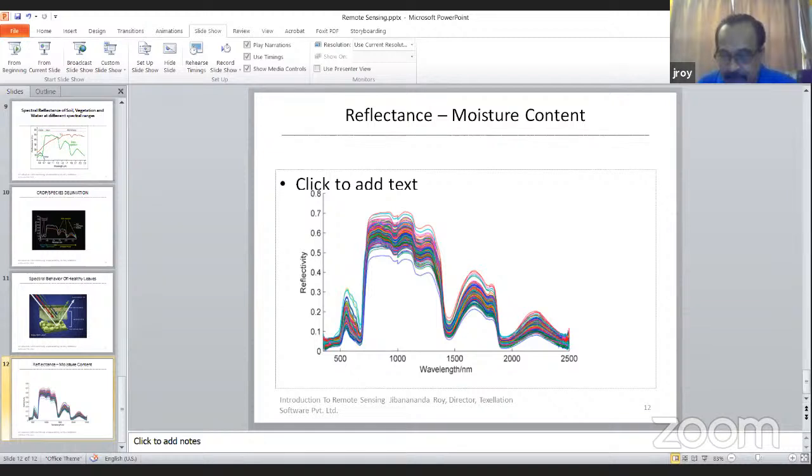So the first thing is pre-processing. That is one kind of pre-processing. What is the other kind of pre-processing? Which is on the image itself. That means due to the curvature of the earth, the image you are seeing is actually the projection of a 3D surface. So you will have a lot of geometrical distortions here and there, specifically when there are hills or hilly areas and the plains.